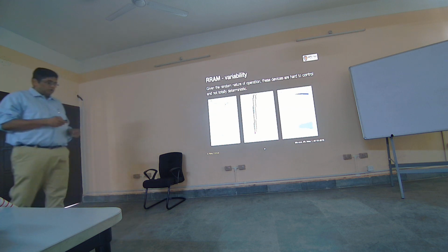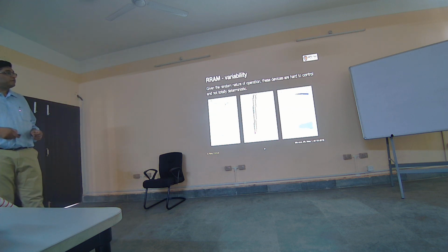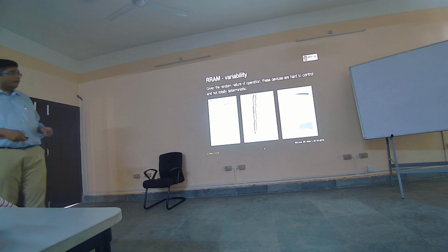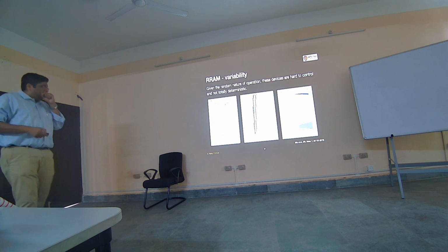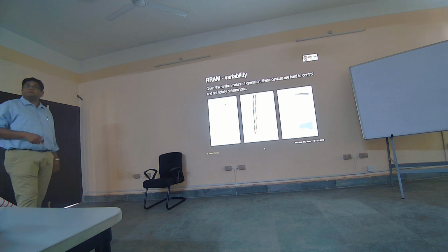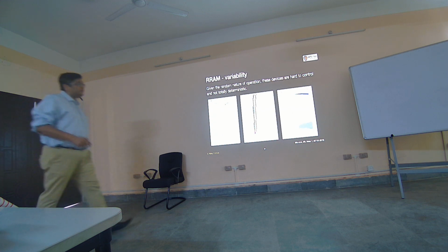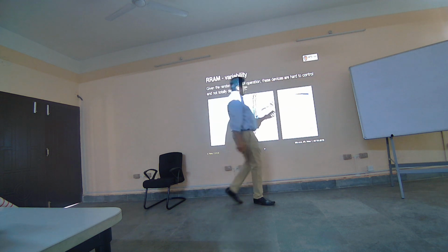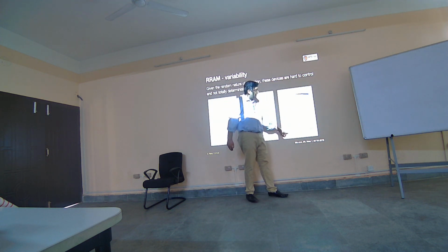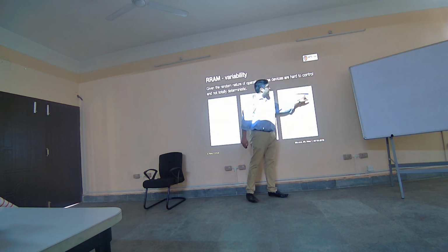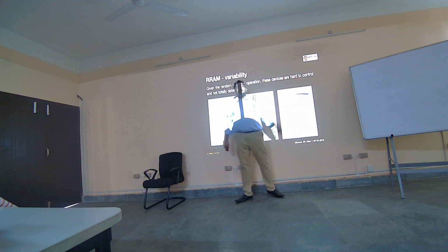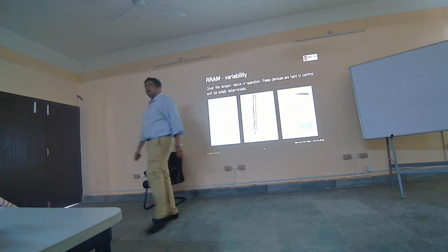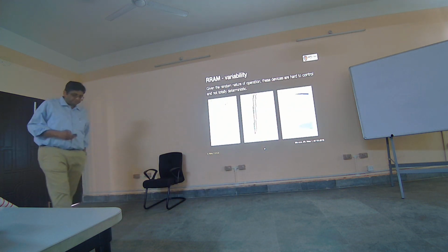Here is the cumulative plot showing the variation in set voltage. And here is the variation for a particular oxide, say hafnium aluminum oxide. You see here that as you change the switching cycles in the device, the current is dropping. So this is the variation in the device that you need to be aware of and that you need to factor in when you're designing the circuit.